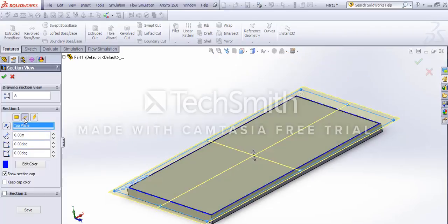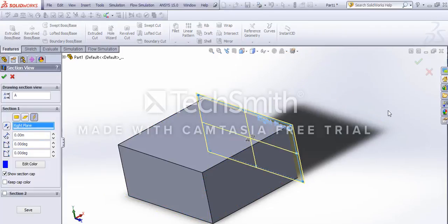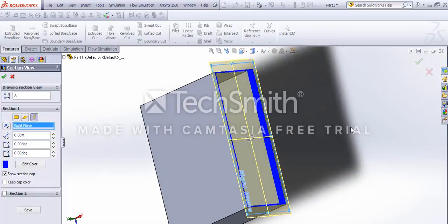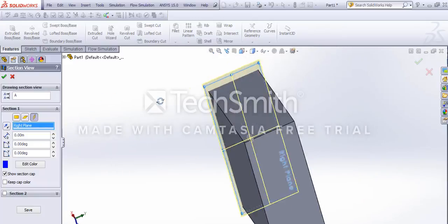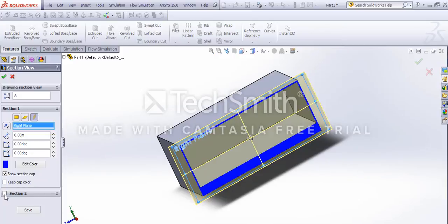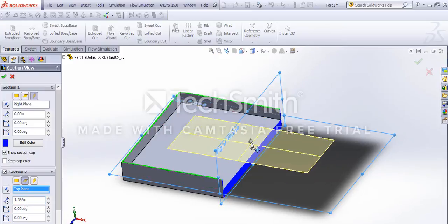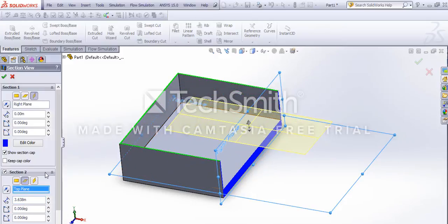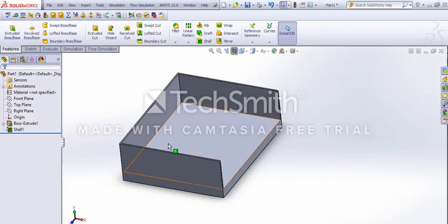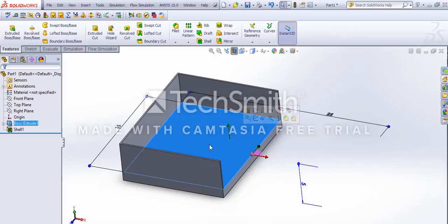Now here we can choose the standard 3D planes for the section plane, or you could change to some other area, even 2-dimensional ones as well. Like if we choose this one, this would cause the top plane as well as the front right plane to be the section planes. Now let's make a drawing on this plane.